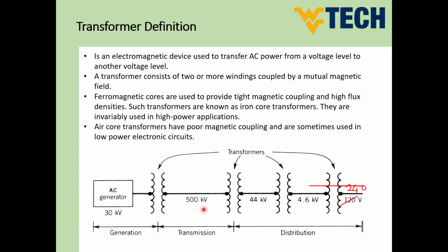So definitely, guys, power will not increase during transmission. It could reduce because you will have losses during transmission. So if you assume that you have, for instance, 1 gigavolt ampere to be transferred, we can transfer this 1 gigavolt ampere through 500 kilovolt, for instance, or maybe higher. So why? In order to reduce the current.